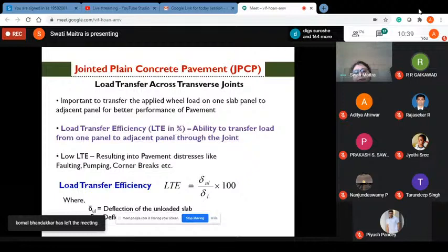So for that we have to do an axle load survey to know the range of loading on the highway. The design traffic volume survey is done based on a 7-day, 24-hour count, and an axle load survey for single, tandem and tridem axle loads. And when we do these surveys, we do it for a design period of, say, 20-30 years or so. So you also have to use the traffic growth rate factor.